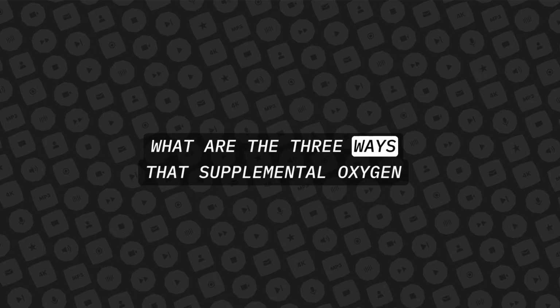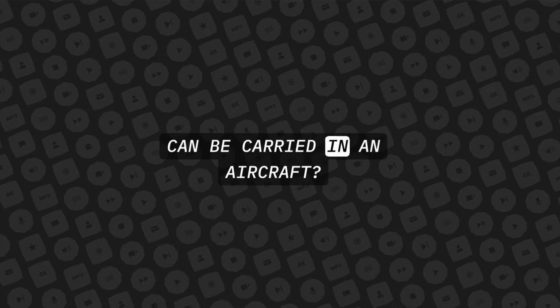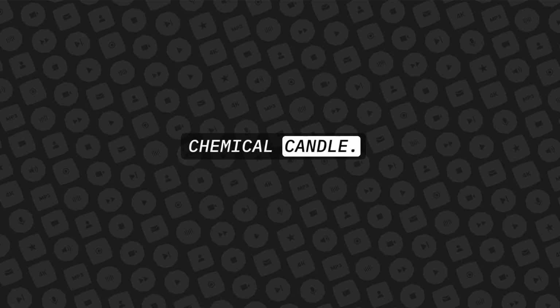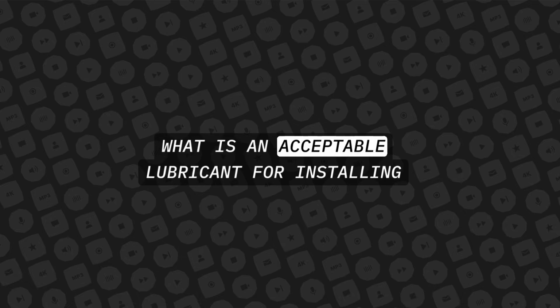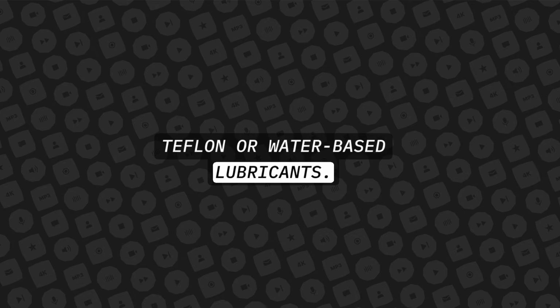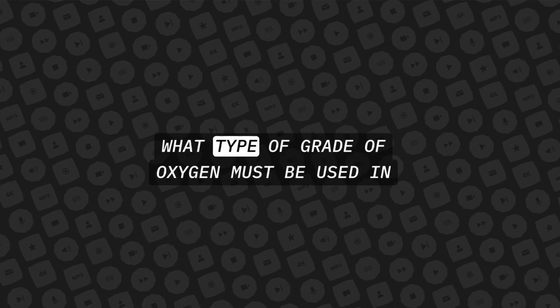What are the 3 ways that supplemental oxygen can be carried in an aircraft? As liquid oxygen, a high pressure gas, or as a chemical candle. What is an acceptable lubricant for installing oxygen system fittings? Teflon or water-based lubricants.